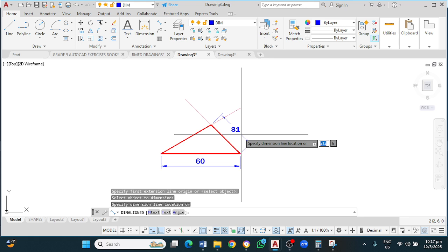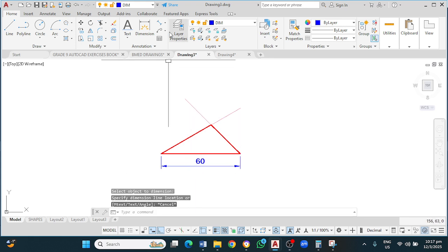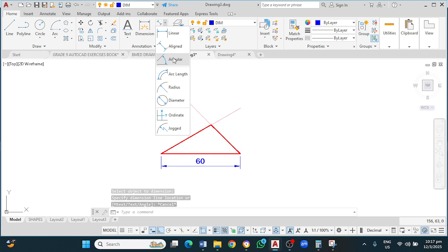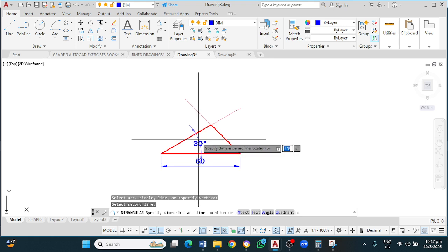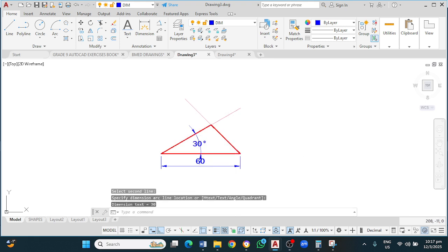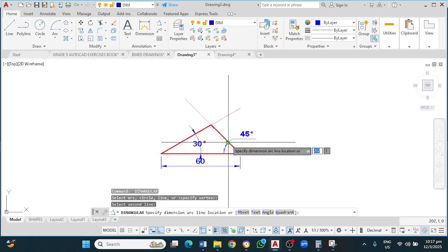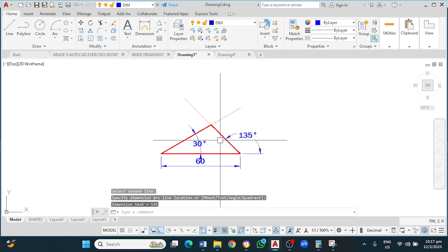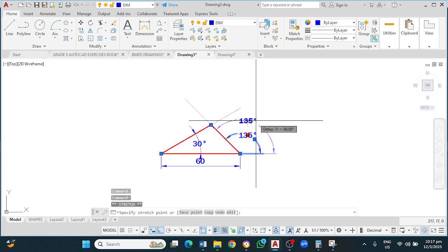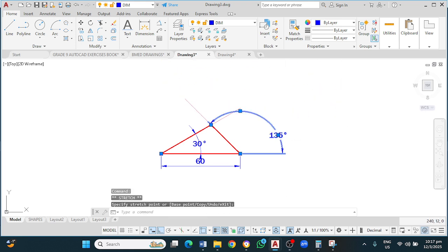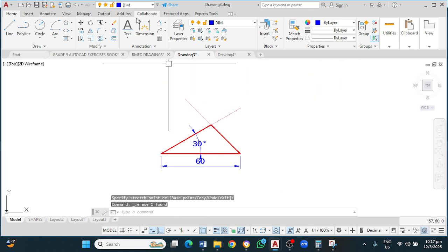Oh, they give us the base and 2 angles, so you need to do what they say. For angle, I left click there, left click there. That is that, space bar. Oh, undo. Alright, bring this inside. Delete. Let me go back to angle.